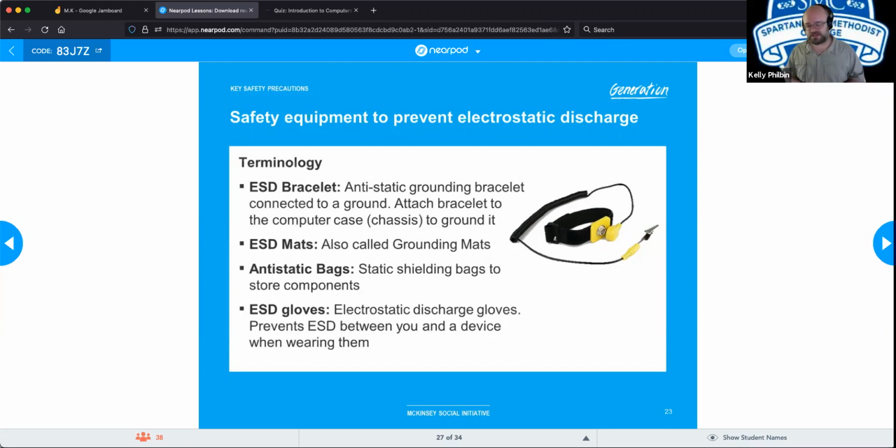Well, it's mostly you neutralizing your charge between you and the actual machine when we have the ESDs. And when they're speaking about grounding out, it would be if it's still powered on and then you ground yourself out on it, that's where it gets bad. So we want to negate the charge before we ground ourselves to it. You don't want to ground yourself to something that's powered on or attached to a power supply. That's why I say power it down, disconnect it, then attach your ESD bracelet. You don't do that before everything is shut down and disconnected. A good question, it is a little bit nuanced though.